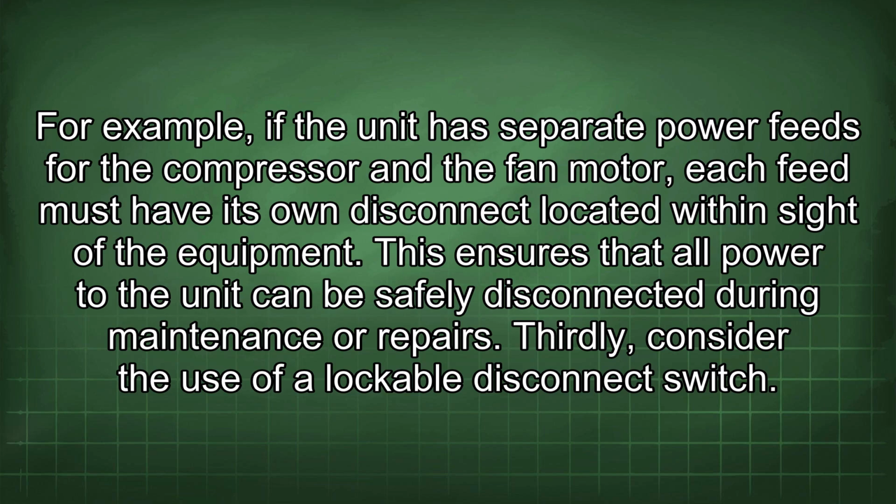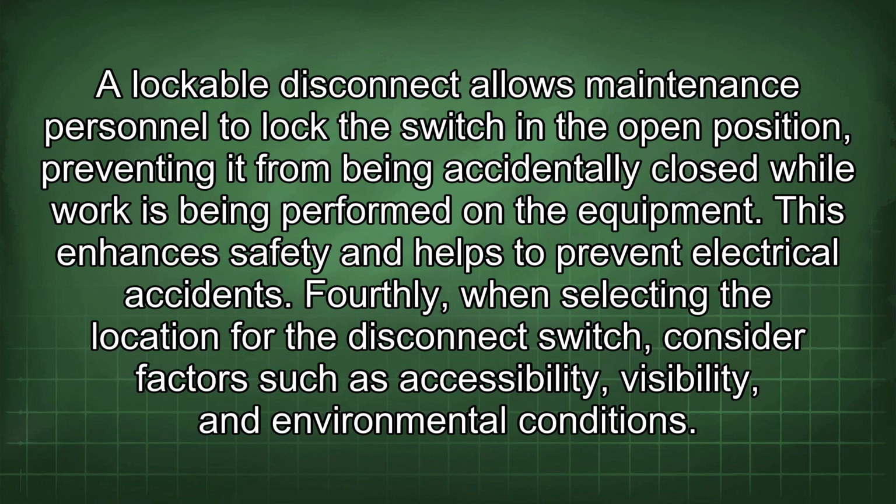Thirdly, consider the use of a lockable disconnect switch. A lockable disconnect allows maintenance personnel to lock the switch in the open position, preventing it from being accidentally closed while work is being performed on the equipment. This enhances safety and helps to prevent electrical accidents.